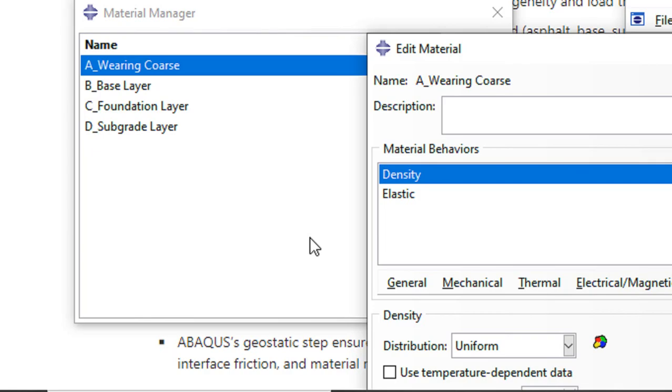And for deformation analysis or stress analysis, pore pressure is important, for which you need to define an accurate mesh model with coupled displacement and pore pressure degrees of freedom, so that you can simulate consolidation as well.